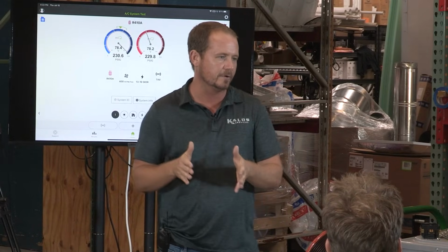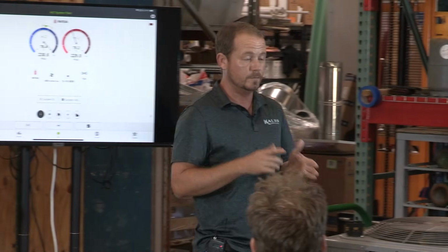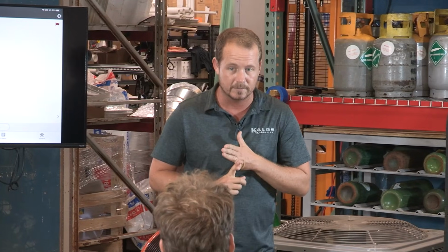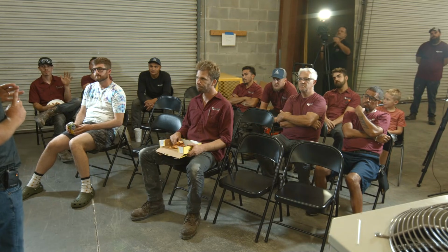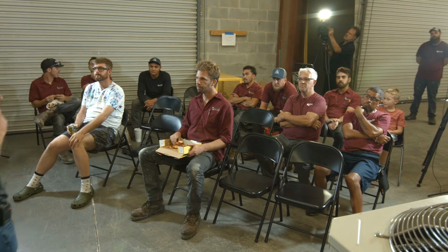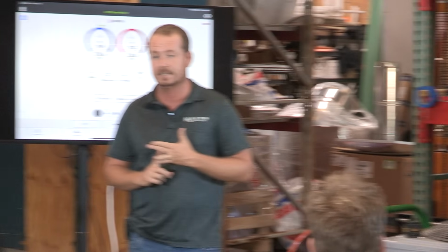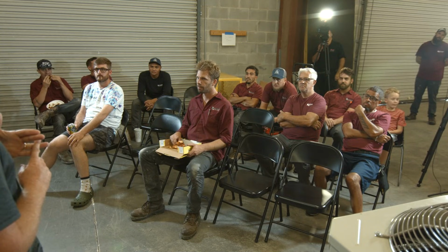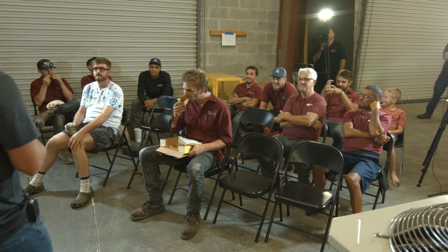So if you have a PSC motor that's making a noise, could be the bearings on the motor, could be the blower wheel. In fact, often it is the blower wheel. And what often happens on a blower wheel that makes it noisy? Eli? It breaks. Yes, the hub breaks. The hub gets loose. The hub gets loose.